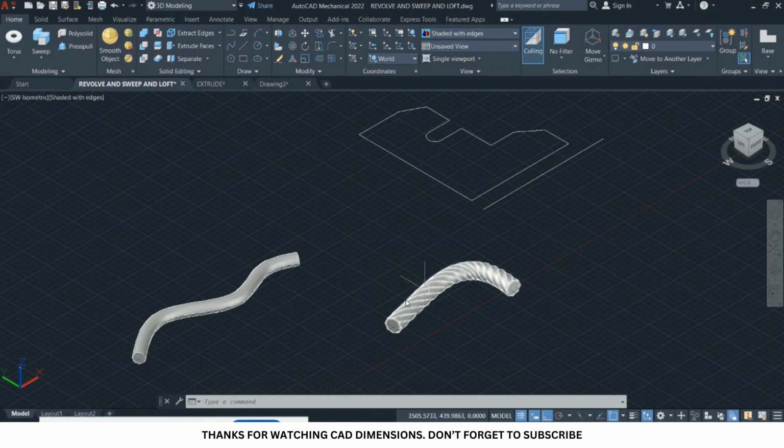Okay, so that is one thing with the sweep. You can twist the shape that you are going to sweep across the open path, and you can also use the scale, where one end would be larger than the other. So let's look at the scale that I'm talking about.